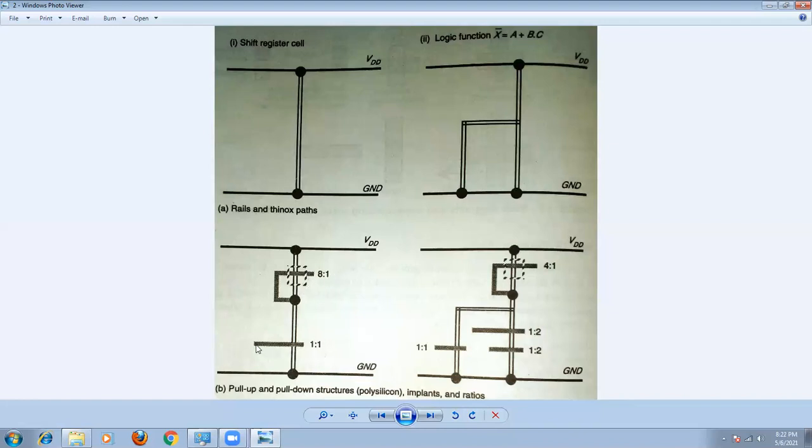Similarly, we form a transistor. Then the final step is contacts. This is the metal one, and this is also a metal one. This is the polysilicon. This is the diffusion layer. Metal with any layer, you can use the ordinary contact. Basically, the color is black. Similarly, here also a normally black color. This is also black color. So between metal and diffusion, a contact will exist.